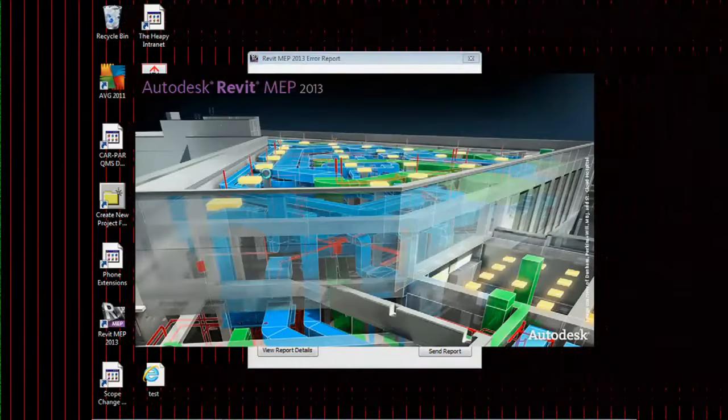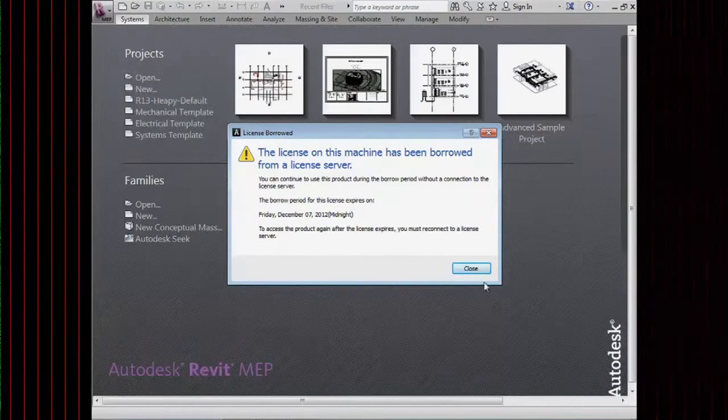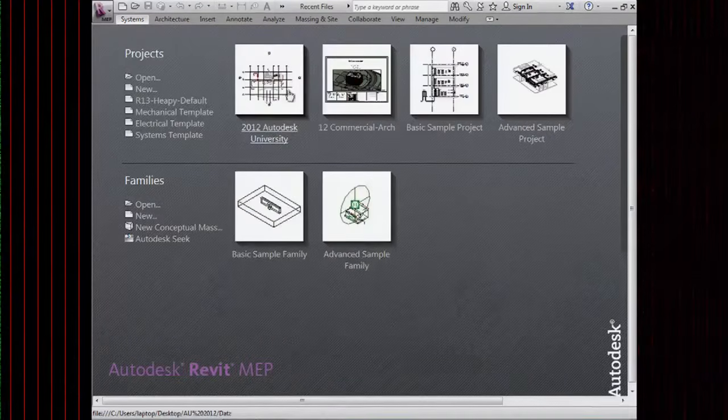Calculations are turned on. If you turn calculations off for that particular system, the system inspector tool doesn't work, because it's basically saying there's nothing to report back to you. The blue path is the non-critical path. So again, system inspector is a handy tool that will point you in the right direction.